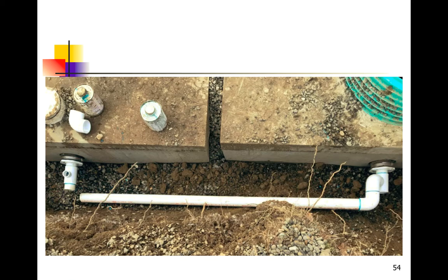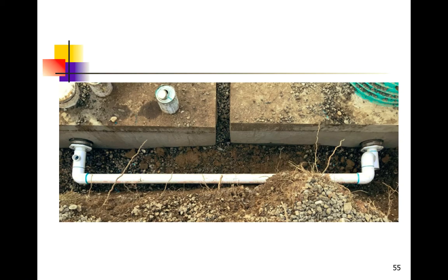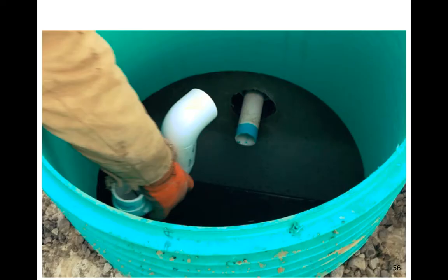So we have what we call a double 90 arrangement there at the recirc tank. And then our last connection will be the 90-degree elbow going into the discharge tank. At this point, the plumbing between the two tanks is complete, and we don't need to do anything else to attach the tanks. But now, inside the recirc tank, we're going to have a 2-inch stub.